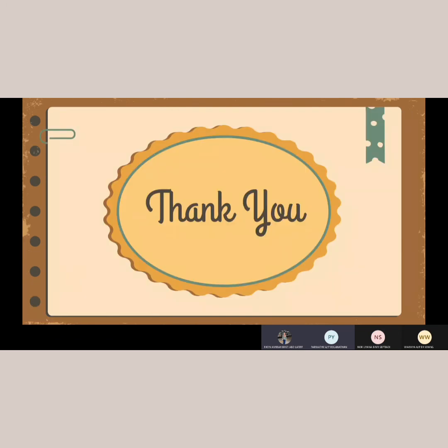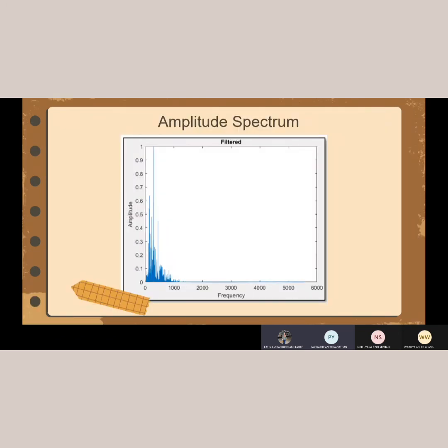For the original unfiltered audio signal, the FFT function is applied to view the amplitude spectrum of the signal through the plotting process, and the spectrogram function is used to see in a visual way the signal strength and noise loudness over a time frame of frequencies. At the first filter, the notch filter is applied to reject or block the transmission of frequencies within a specific range and allow frequencies outside the range, to filter out the high amplitude noise at high frequency. The second filter uses a band stop IIR Butterworth filter at the frequency range between 1700 Hz and 3300 Hz. And the noise gets eliminated better using a low pass IIR Butterworth filter.